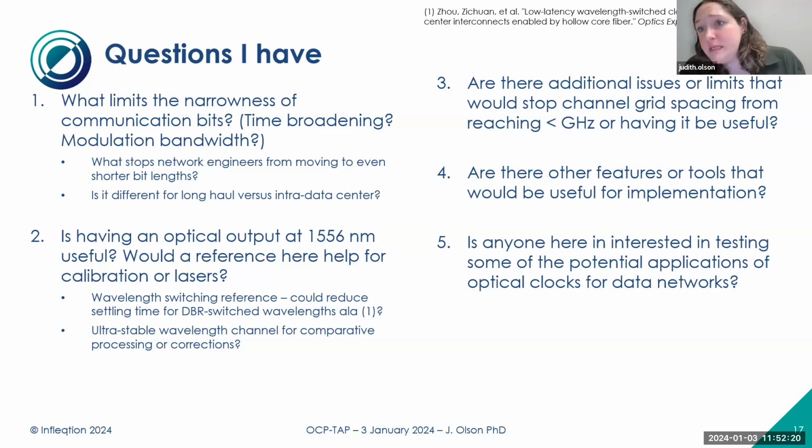So the further away from DC you can measure, the better your measurement will end up being. If you're trying to measure a change from DC, it's not great, but you can intentionally offset your clocks by however many megahertz and then measure that beat note. I imagine you could see it pretty quickly. We can tell resolution far below what is typically used in the optical. So we can start seeing hertz level differences in these clocks pretty readily.